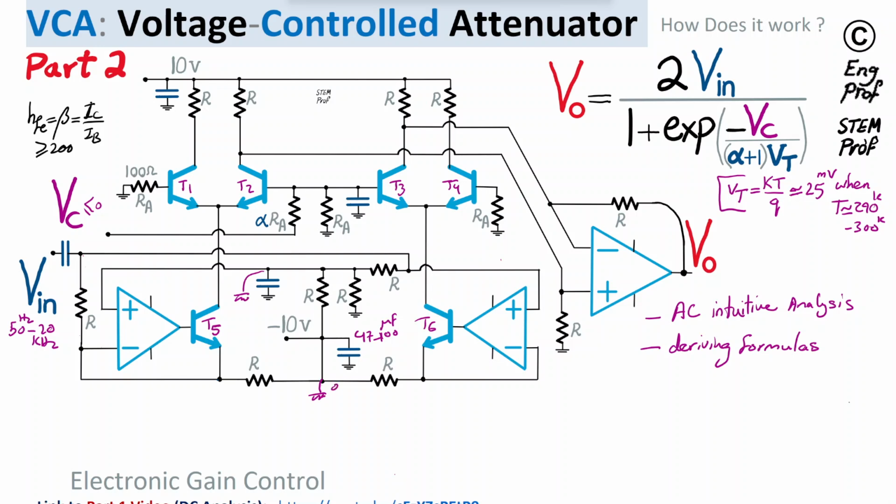So we have 0 volt here and at this common node, and just reminding what was already discussed in the DC analysis part 1, negative 10 volt and plus 10 volt are the dual DC supplies used in this design. So from AC standpoint, this node is virtual ground, this node is virtual ground shorted by the cap to the actual ground, which is exactly as the positive terminal of the op-amp. So we have AC virtual ground at the positive terminal.